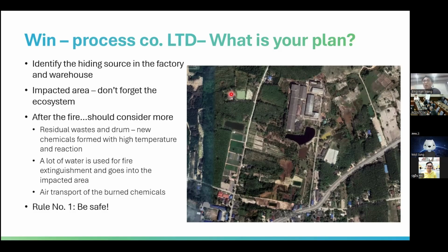And of course, for the lagoon, you have to take a groundwater sample and a sediment sample, but it is not easy because the lagoon is very, very deep. So if you cannot take the groundwater sample, just take samples around the lagoon to figure out if the surface layer is contaminated or not.